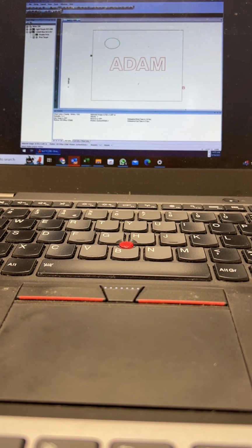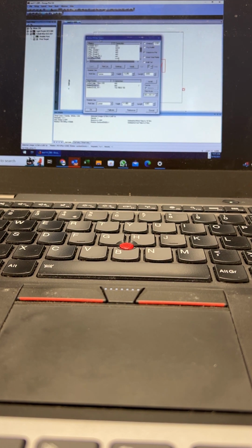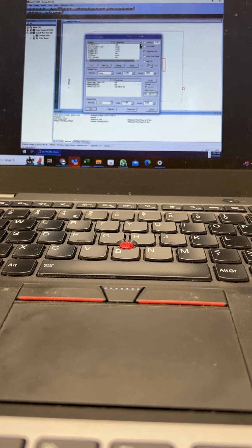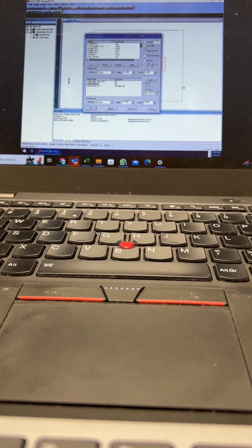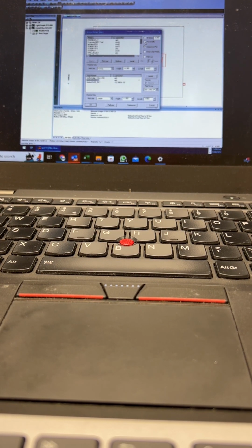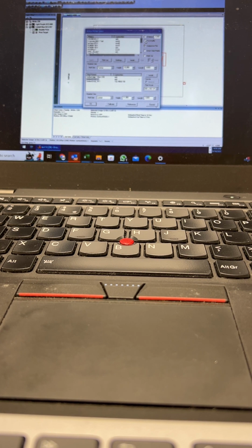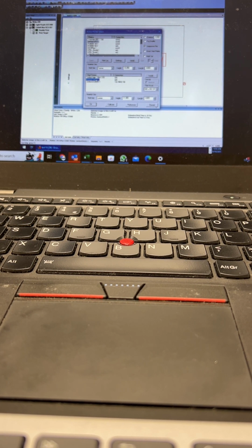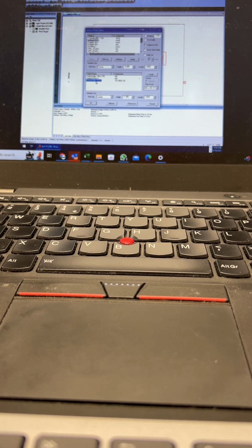This little device here with a little eye on it, that gets you to your plotter printer selection. So this lists off all the plotters that I currently have installed. In your case, when you're doing a new install, you're probably going to have 1, maybe 2 plotters. Most sign shops will have a 15-inch Gerber plotter, and then maybe a 24-inch or 48-inch friction plotter, Graphtec, Mimaki, whatever. So you'd select that plotter. So if it was an Envision 375 you installed, you'd select that, and the edge that you're going to output to, whether it's an Edge 1 or 2 or the Edge FX.